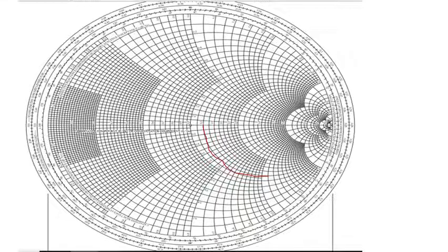And then minus j1.6. Minus means capacitive, if you remember. So this thing will go down. I'm here. So this is 1, right? This line is 1. So it becomes 1.2, 1.4, 1.6. Why am I looking down? Because it was given in the problem as minus j1.6.